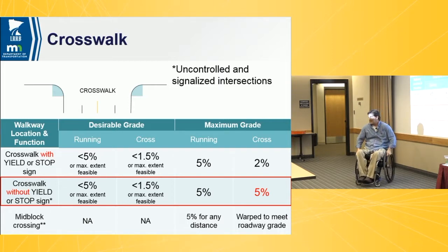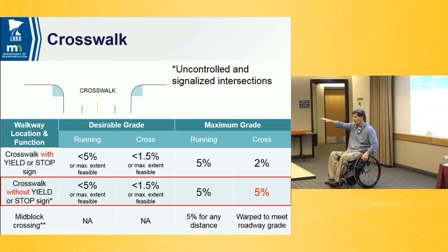So what we're saying is, if you're coming down that same road and you're coming across a side street that is already crowned and tabled, so you're already coming down and going up and through this intersection, so there's already a large bump there. All we're saying is you should extend it through those crosswalks. So you give the pedestrians the same benefit you're giving that car for that side street. So we're holding that 2% through the whole intersection, and we are going to table out the crosswalk, because the whole intersection is already tabled out.